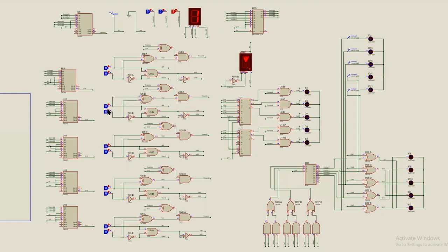What if someone from the 4th floor wants to go down and someone from the 2nd floor also wants to go down when the elevator is on the 1st floor? Being that the 4th floor is the furthest one from the elevator, it will go towards it, and its trajectory is now upwards. It will not stop on the 2nd floor because the 2nd floor's desired trajectory, or where the passenger wants to go, is not in the same direction as the elevator's current trajectory. So it will ignore the 2nd floor. As we can see, the 2nd floor is ignored. It will go to the 3rd floor, it will be ignored, and the 4th floor is where it will stop.